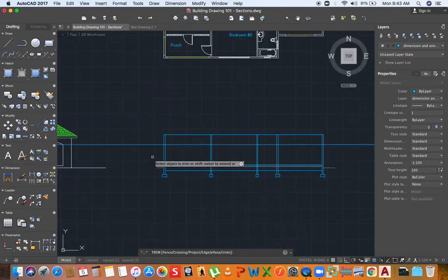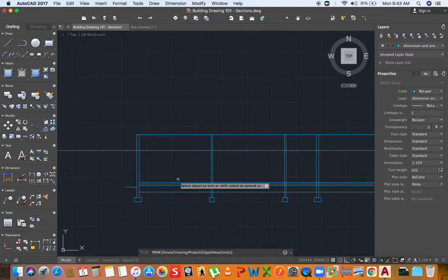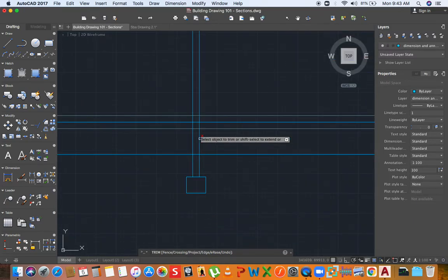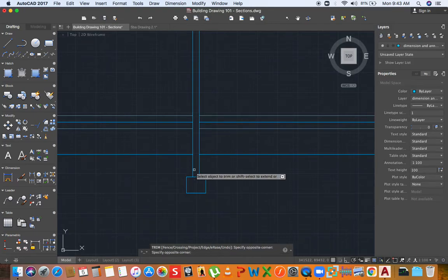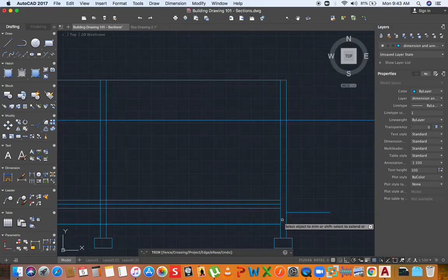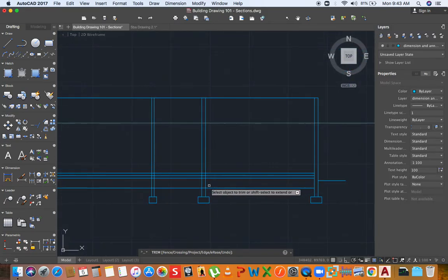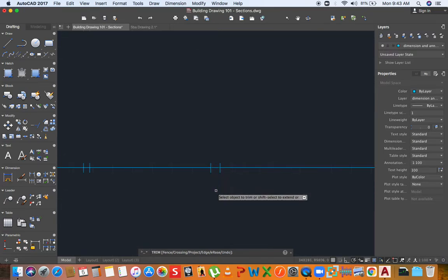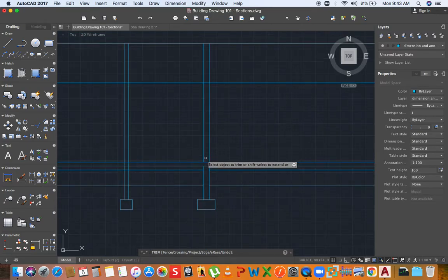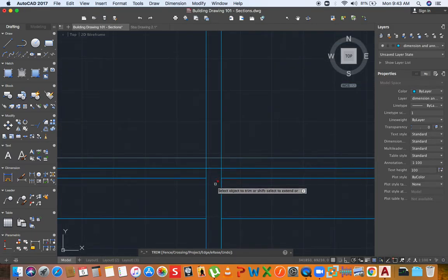If it cuts through a window, it will leave like this. If it cuts through a wall, like right here where the mouse is right now, we are going to trim out all of the part of the wall here. Right here, it's cut into a wall again, through a wall, through a window. Whether through a wall or through a window, you trim everything because the wall doesn't come all the way to the ground. If this was a door, you'll trim everything except this top portion, and you'll trim this here. So it shows that there's an opening there. But there's no opening, so I'll leave it like this.